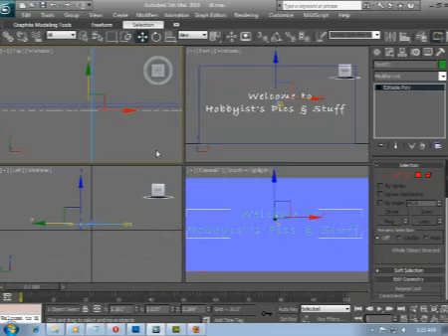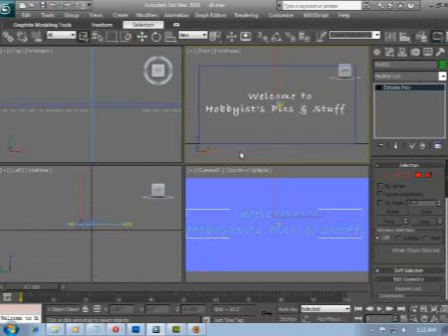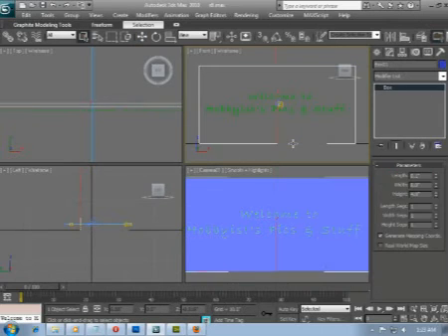Well, we've reached the part where the machine is really going to start lagging during some operations. The reason is that we're about to request the maximum possible number of polygons on our box's front face. We're doing that so that when we extrude the letter shapes, they don't get all flattened and unreadable. Let's right-click in front view and hit Q so we don't accidentally move anything, and select the box.